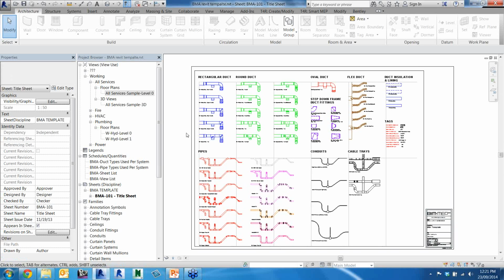It can be noted though that the template can be seamlessly upgraded to 2015 with no problems, particularly with regards to the lookup tables that run the pipe fittings inside of the template as well. As I'm sure you guys are aware, from 2014 onwards, Revit embeds those lookup tables into the fittings themselves now, which we have done with these template fittings, so that when you update the template from 2014 to 2015, you don't have any dramas with missing lookup tables or the like. It should just update quite seamlessly. But as I said, this is 2014 that we've got open here at the moment.